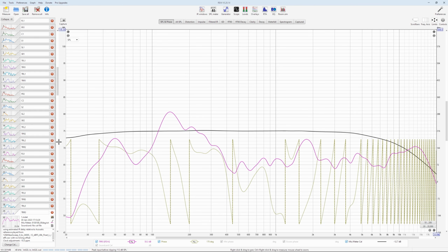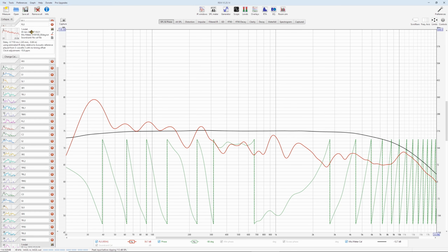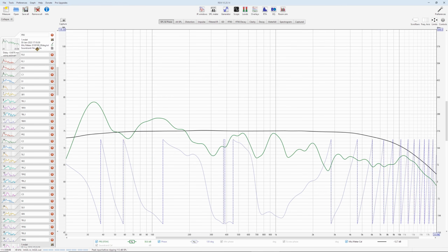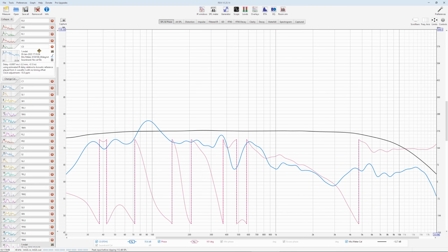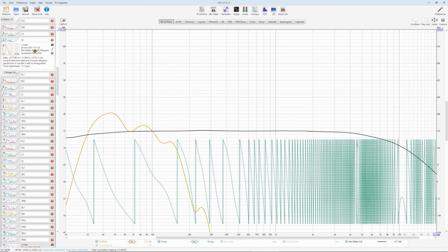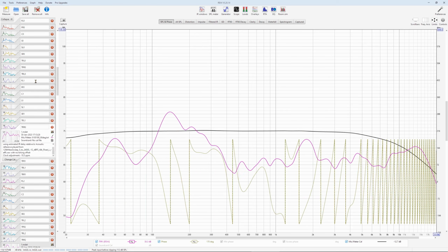We have to first cross-correlation align the measurements to each other, because cross-correlation align prioritizes the one on top of the other measurements as the original measurement. So you have to carry up the ones with 0 in this. The last measurement at the central listening position has to be on top of FL1 and 2. This is the only way, manually carrying them on one by one. Subwoofer 0 goes above every other subwoofer measurement. And top rear right, finally.